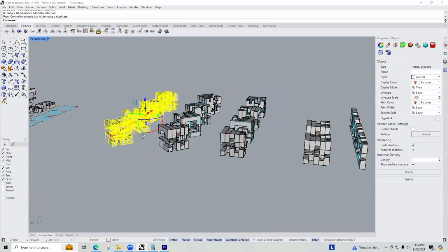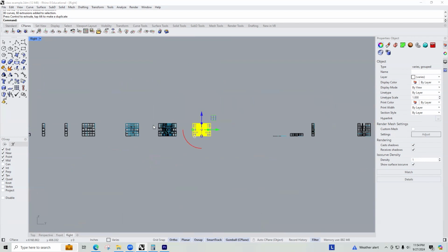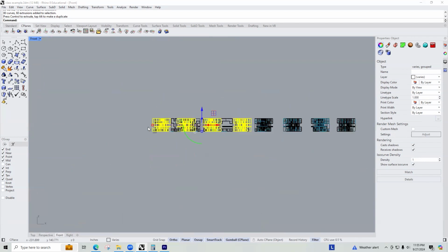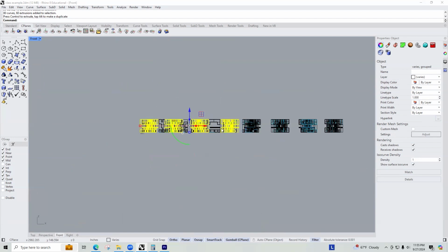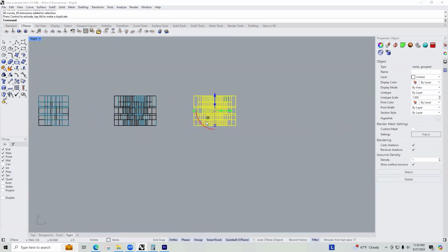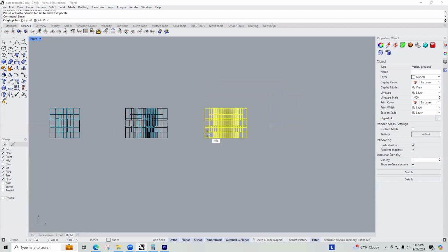So taking it back once more, and then this time I'm going to change it to the, not the top view, I'm going to go to the front view. Actually, the right view is better, sorry. So then I'm going to my right view, and I'm going to type in the command shear. All right, so shear is basically allowing us to lean or taper. So it's creating a slant in our massing.